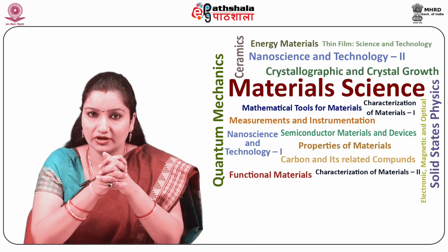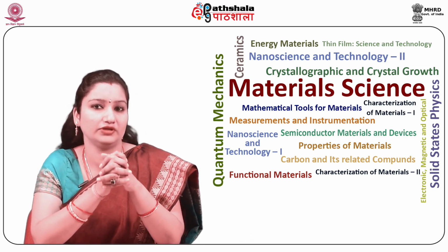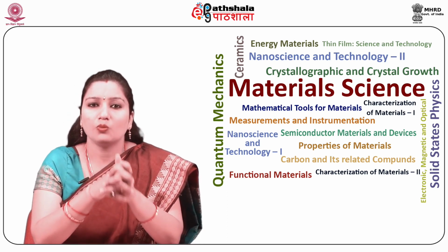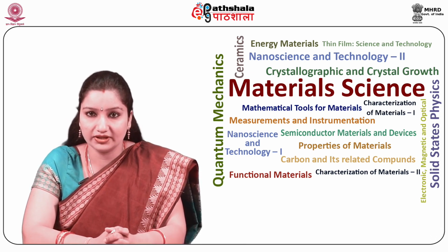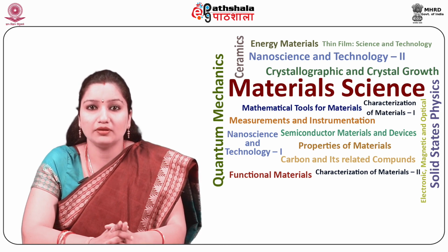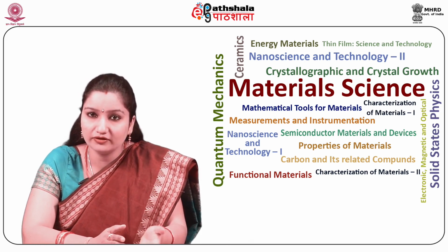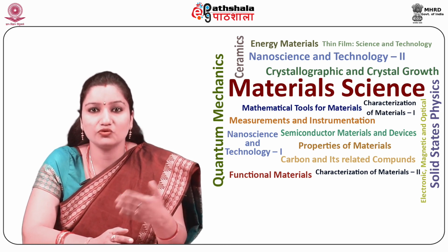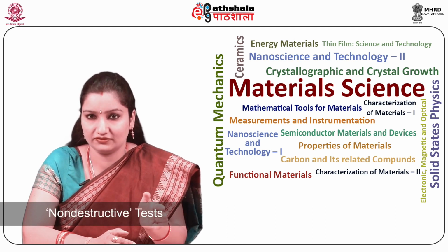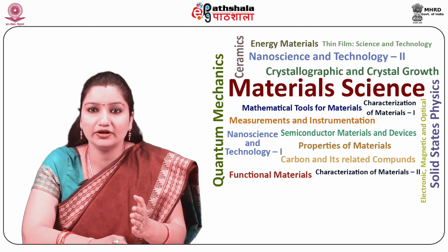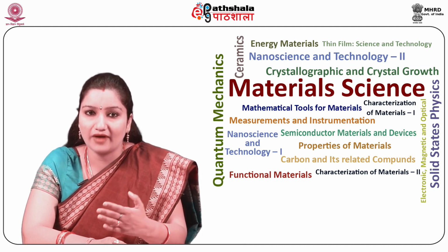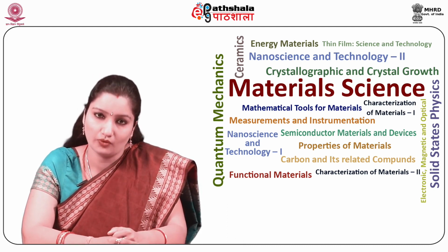Shock loading has the values ranging from 12 to 15. One adopts the lower value of factor of safety by ensuring the metal to be without any defect, which is done through non-destructive tests. In determining the reliability of the design, the factor of safety is of great importance.